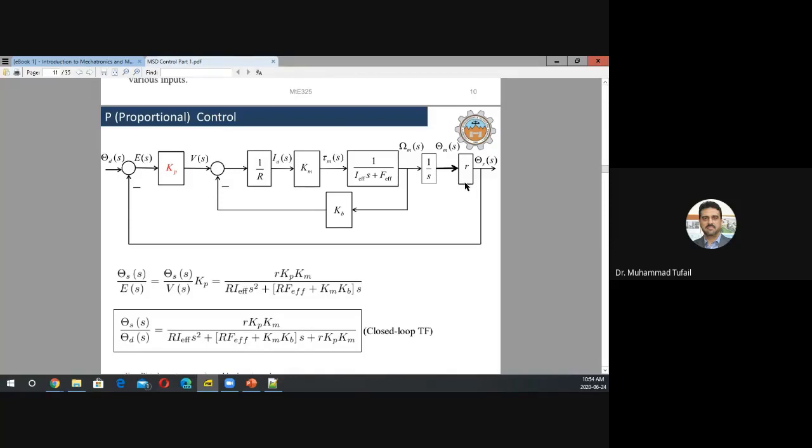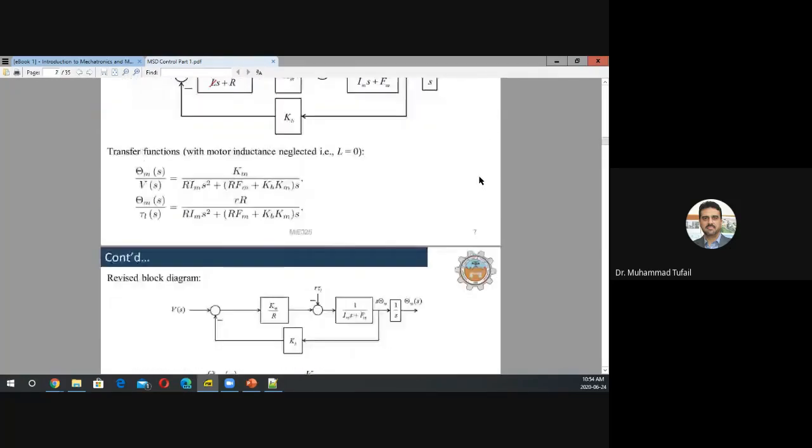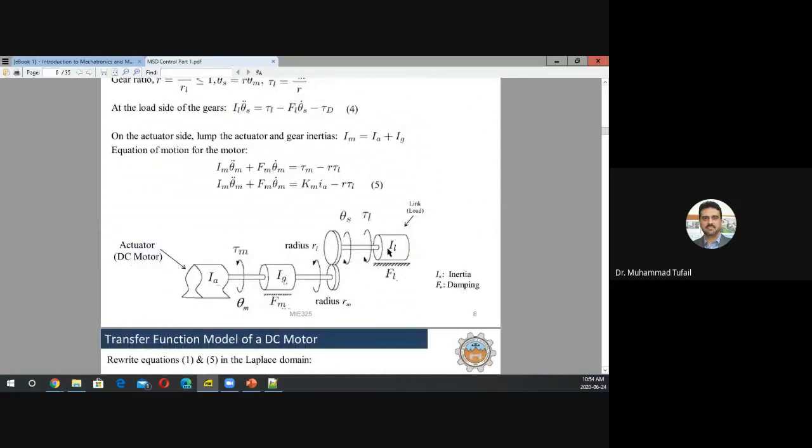थोड़ा सा मैंने यहाँ पे एक ब्लॉक इंट्रोड्यूस किया R. उसकी वजह ये है कि we sense normally quantities to the right of this gear system. Let's say अगर ये आपका wheel है, ठीक है, तो आप wheel के ऊपर इधर optical encoder install करते हैं. You measure this theta of the shaft. You don't normally measure the thetas or anything to the left side of the gear. ये gear तो normally DC motor के अंदर ही built in कर दिया होता है हमने, ठीक है. So whatever we measure, we measure this. So इसका मतलब है कि you're not measuring this, you're measuring this.